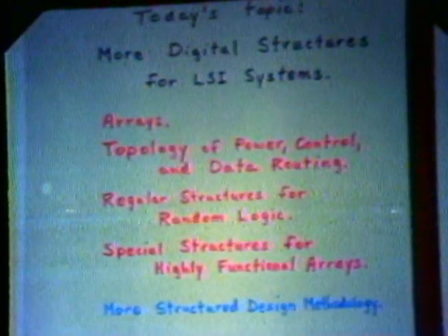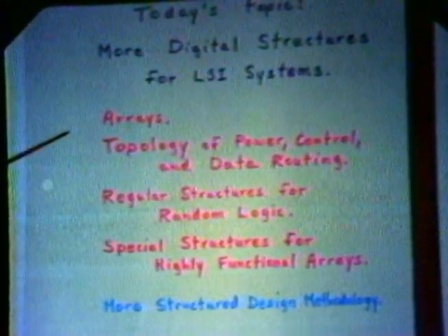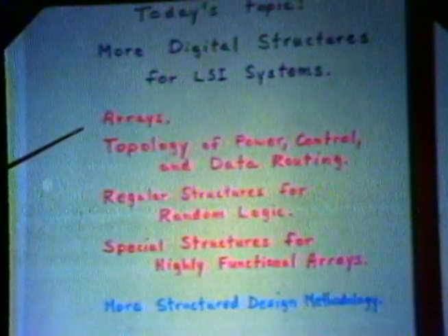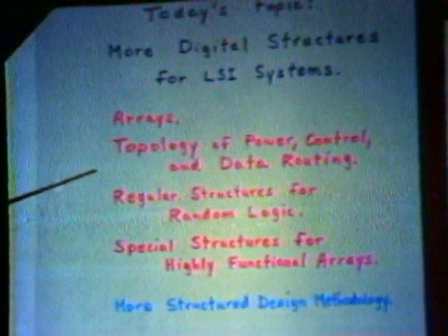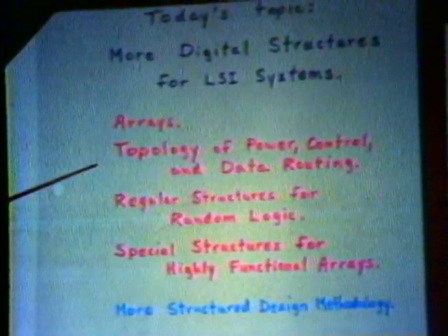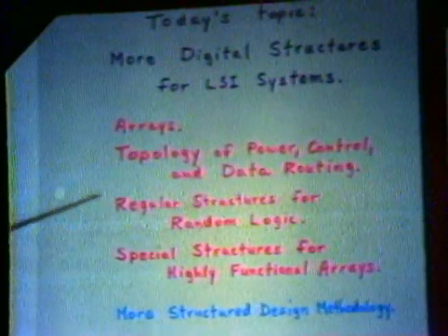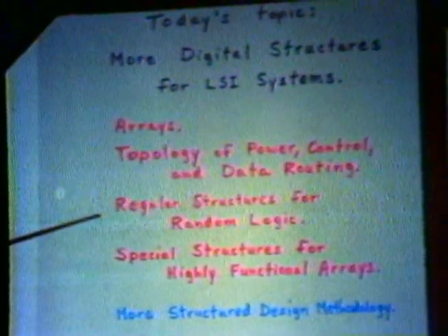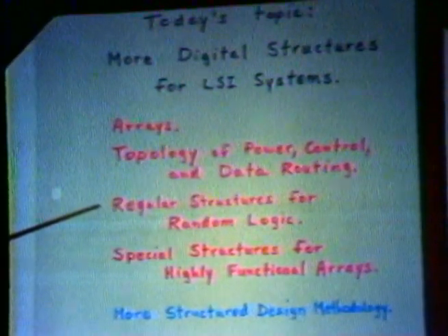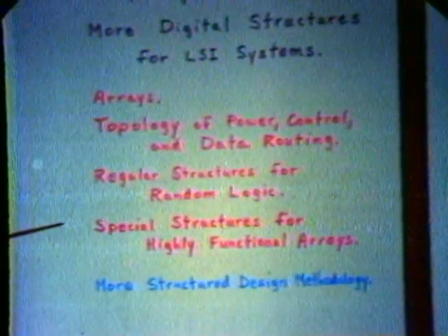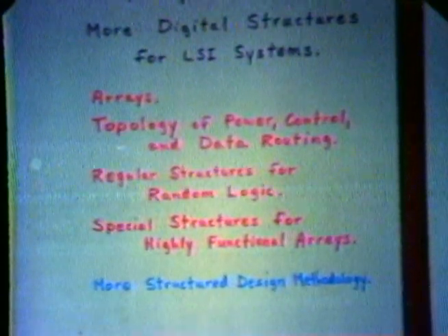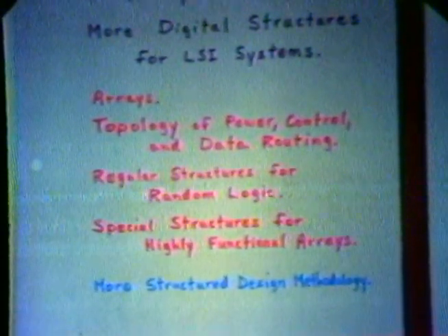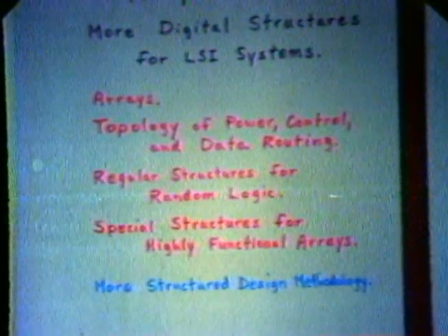Several of the topics we'll be covering today are arrays, which is a very powerful concept for making any kind of logic more structured. The topology of routing of power and control lines, data lines, and so on through an array. Regular structures for implementing random logic, such as read-only memories and programmable logic arrays. And special structures for highly functional arrays. We'll give you some examples of arrays made of custom cells. And I'll mention a little bit more about structured design methodology and the recommended techniques for designing large systems and containing complexity.